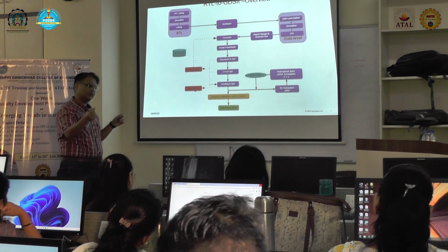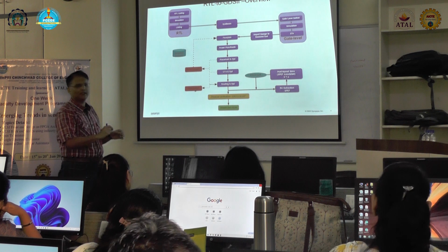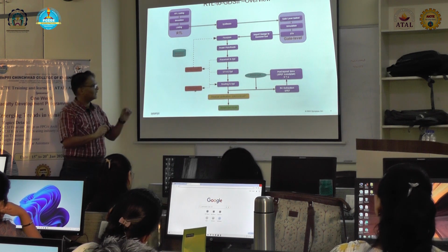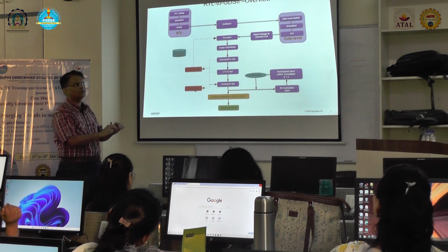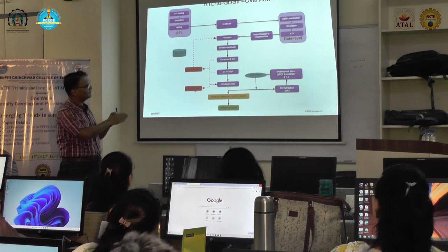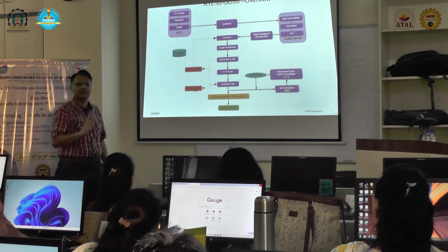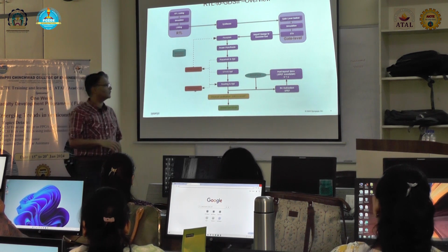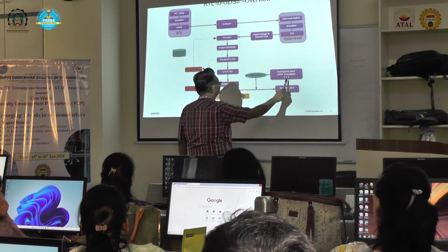We take the gate level netlist and we update the gate level netlist itself. Let us say some more gates are added, and then the ECO is performed. And then you again send it to post-layout sims, and you again confirm whether this logic is correct. So there is a loop here.